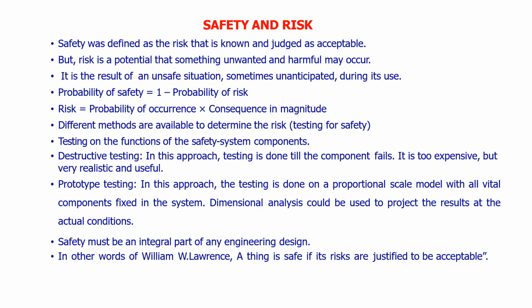Destructive testing is another approach. That is, testing is done till the components fail. It is too expensive but very realistic and useful. In automobile chassis and other important components, we do destructive testing. That is, we load the chassis until it fails. If you are going to manufacture 1 lakh chassis, we have to ensure that the carrying capacity of the chassis is more than enough. That is called destructive testing. Till it fails, we have to load the machine or equipment or any component.